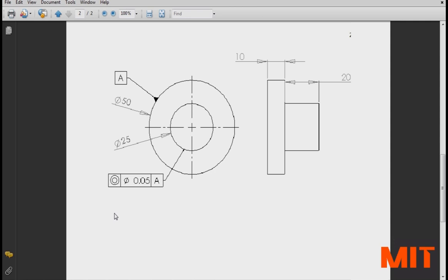So we would use this, again, kind of like in an example like this, where you have a shaft and you have an original axis where you want to create your concentricity from. So again, with concentricity we need our datum. We chose the outer, the larger diameter shaft as our datum to close into the fixture, and from the fixture